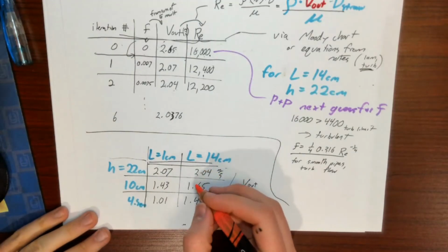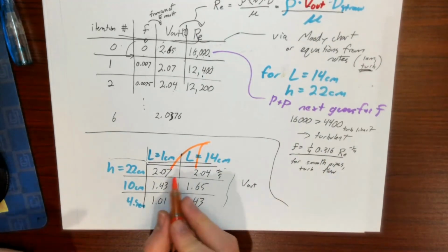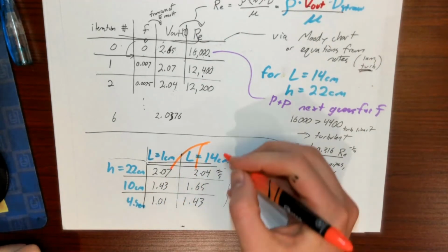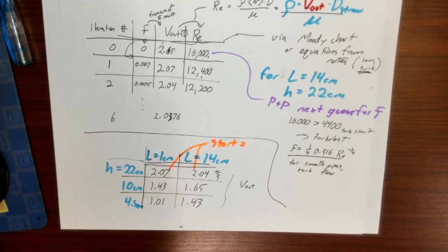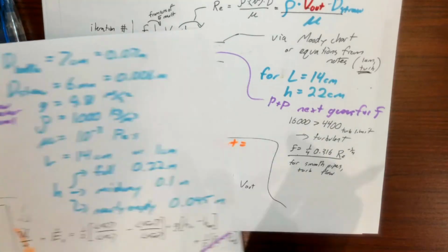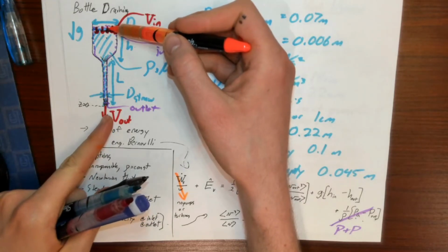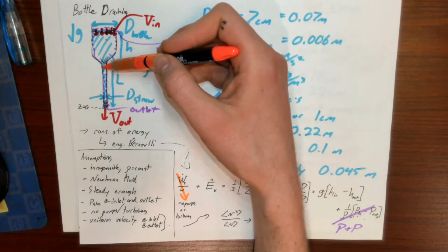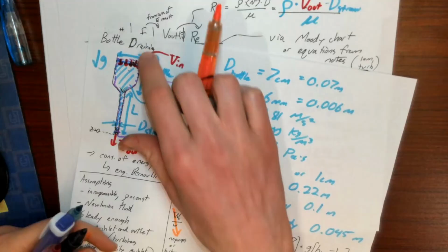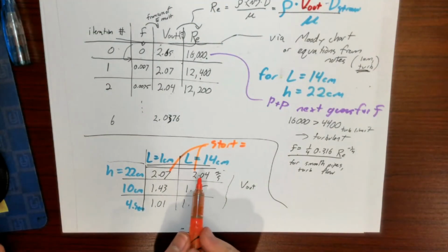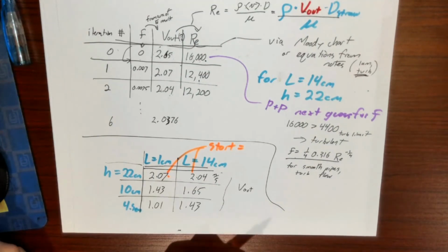So, what are some key takeaways from this process? Well, perhaps you observed qualitatively that at the beginning they start off at roughly equal speeds, and that's somewhat conveniently because the extra potential energy that the long straw gets turns out to be perfectly counteracted by the increased viscous losses from the longer straw. So both short straw and long straw at the very beginning are draining at about the same speed as each other.